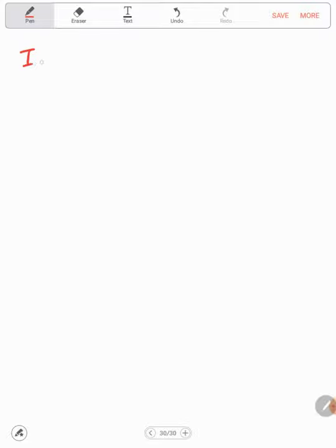So I base will equal S base over square root of 3 V line base, because we are using square root of 3, or we can use 3 and use the base voltage of the phase.